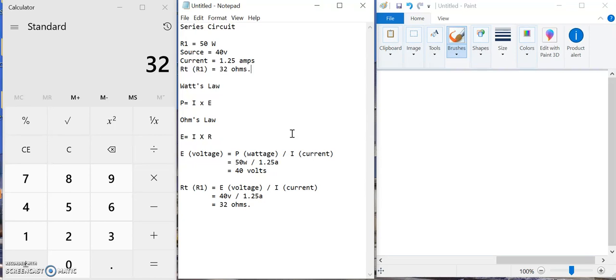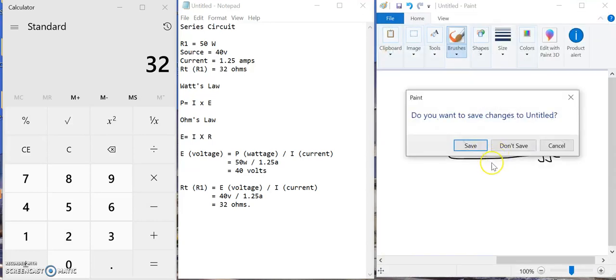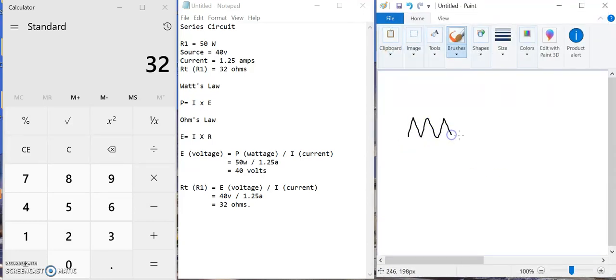So that's really, what am I trying to say here? You'd want to just remember as well, there were a couple of places where people were using the values of one resistor, right? So say we had 10 ohms over here, and then I don't know, a 5 ohm resistor. They were using the values sort of together, which you can't do. If you have two resistors, or 3 or 4 or however many, and you're trying to figure out circuit problems, chunk the circuit.